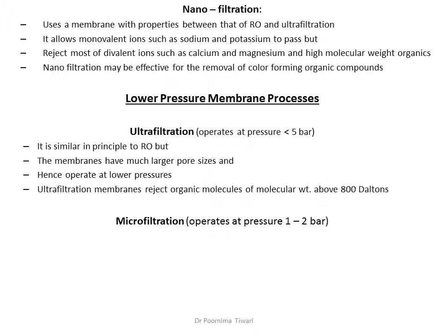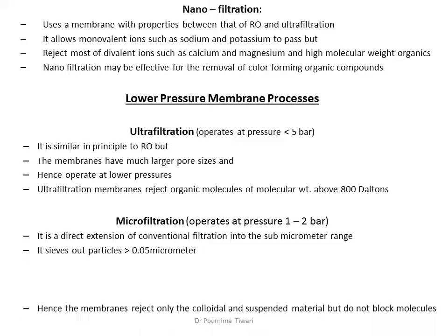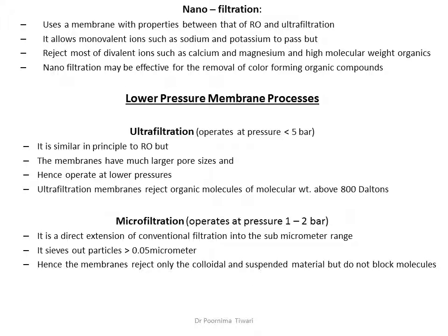Microfiltration has still larger pores and operates at a lower pressure. It can be said that it is a direct extension of the conventional filtration into the sub-micrometer range. It has slightly smaller pores than the filters used for domestic purposes, so it sieves out particles which are more than 0.05 micrometers. Hence the membranes reject only the colloidal and suspended material but do not block molecules.